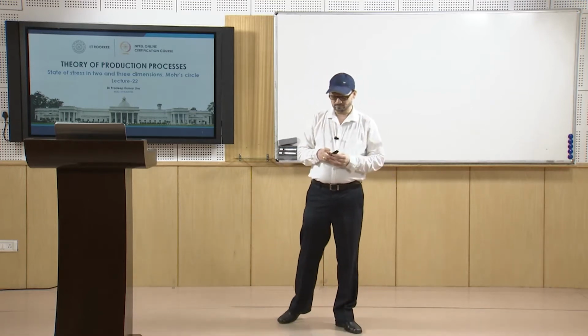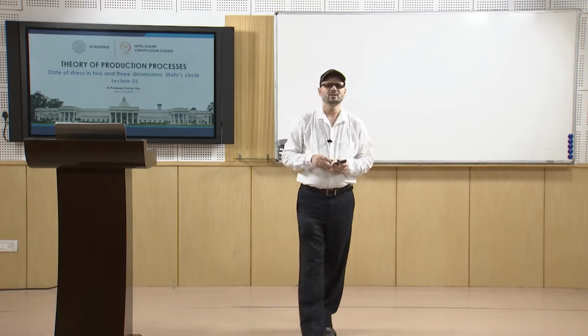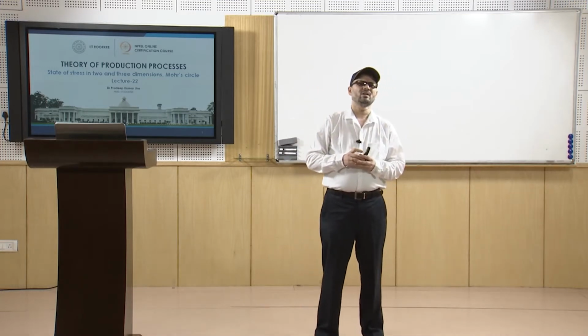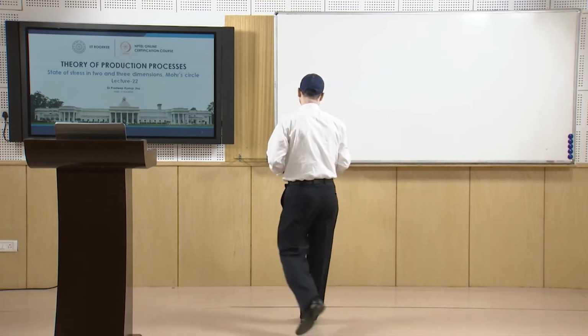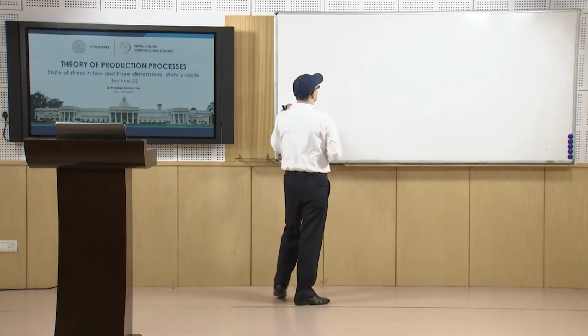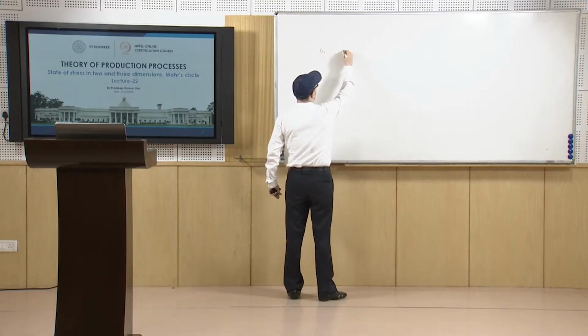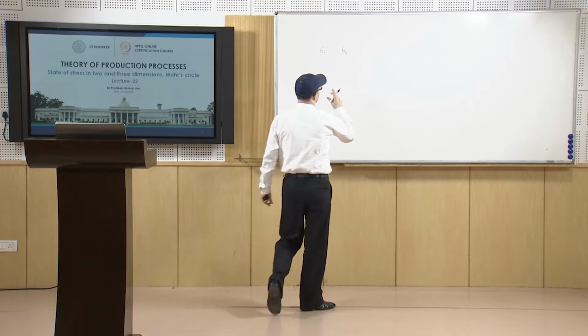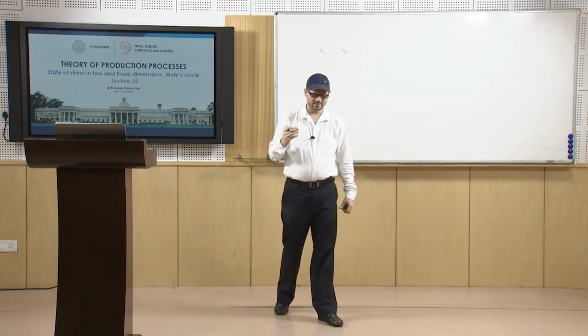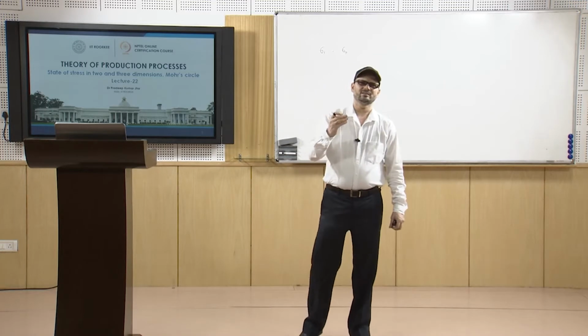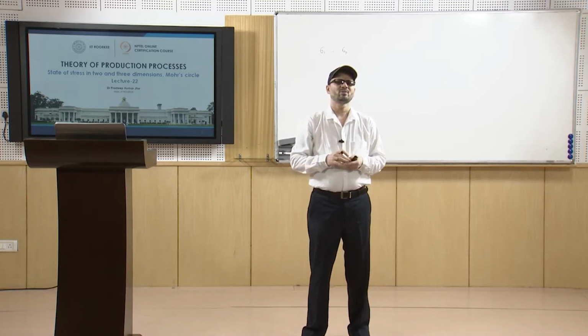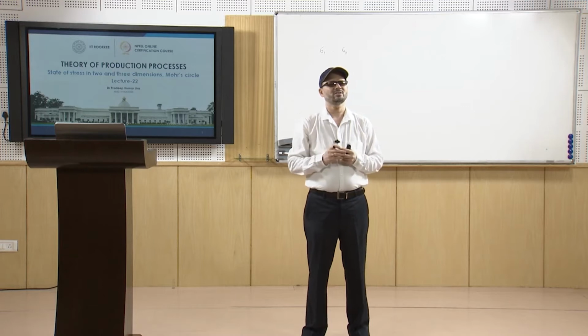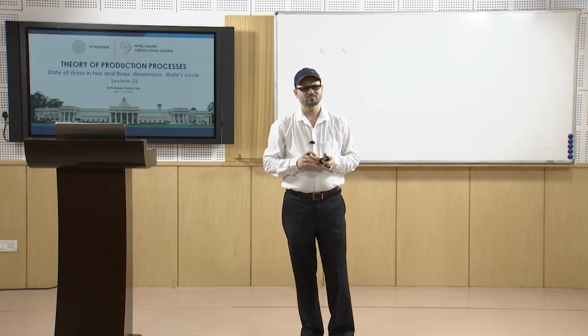The convention is that the normal stresses are defined as either sigma 1 or sigma 1 1, or sometimes sigma x. Normally, if it is tension, you take it as positive, and if it is compression, you take it as negative.